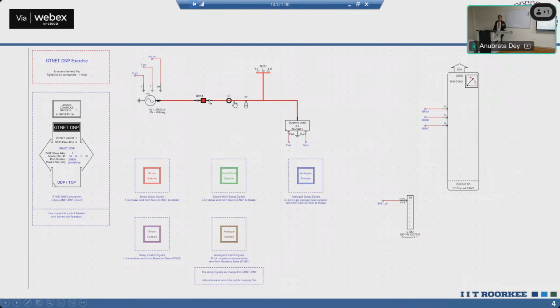After that, we can also model this hardware case, like one RTU via amplifier to a destination. Now the destination is not a PDC. We can use the dedicated RTAC we showed you there as our destination. That can also be used as a data receiver, data concentrator, or receiving device at our end. And for it, we can design our own HMI or our own SCADA system. I'll explain how we can design our own HMI in that. Okay, so that was one of the hardware routes.